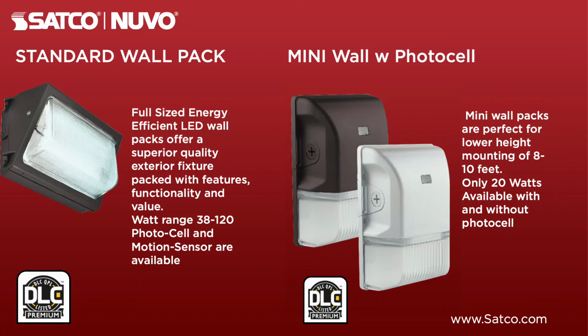Our standard wall pack is full-size, energy-efficient, LED, and offers superior quality packed with features, functionality, and value. Its wattage range from 38 to 120 watts allows it to be mounted up to 20 feet high. Available are photocell and motion sensors. For lower mounting heights, 8 to 10 feet, our mini wall packs are perfect. These are only 20 watts and also available with and without photocells.